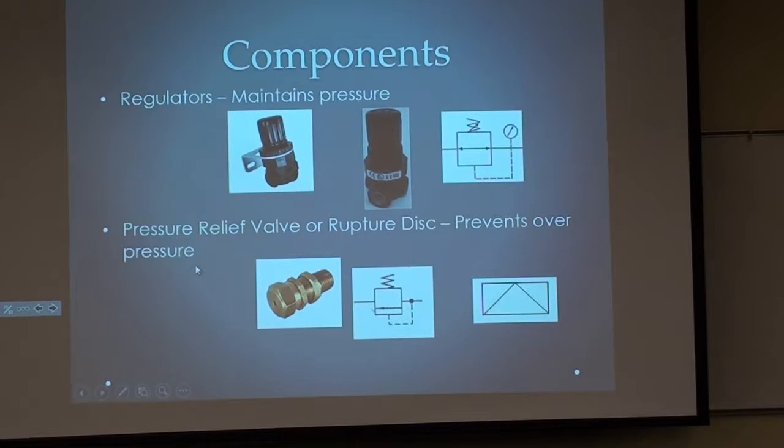What happens on a rupture disc? You might know. Once it blows, you have open atmosphere, and your system doesn't work anymore, okay? So if it was me, I would never even consider one of these. I would always use the pressure relief valve.